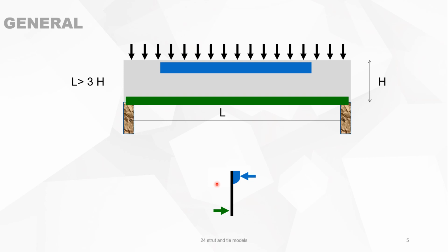So this stress distribution is valid around the middle of the beam, and all concrete tables are created for this situation. We call this zone the B zone from Bernoulli. It's the Bernoulli zone because a section before loading stays a section, or a plane before loading stays a plane after loading.